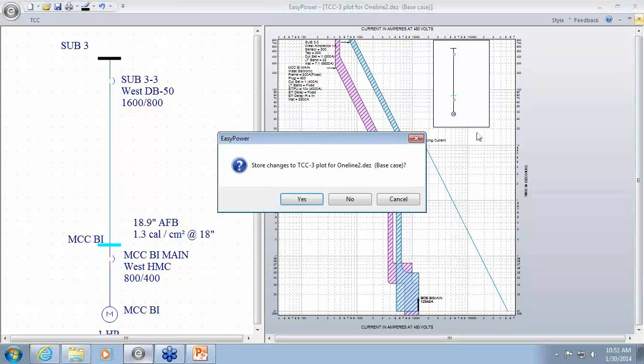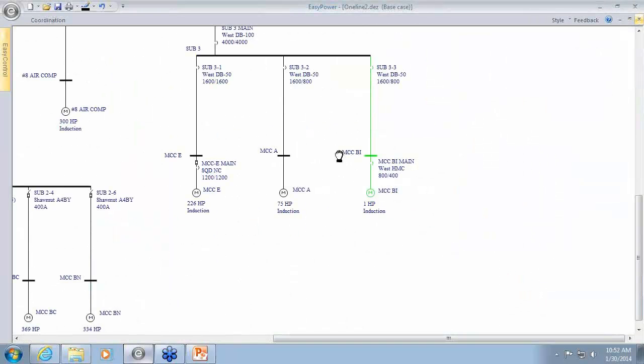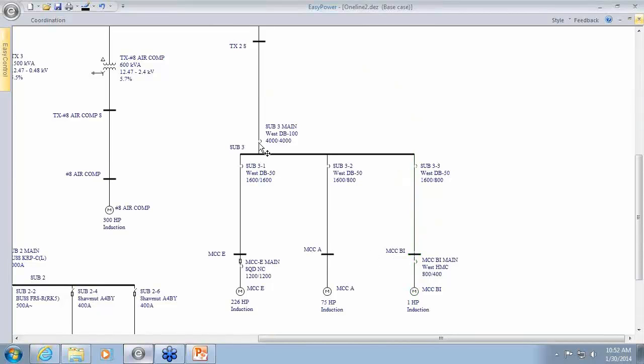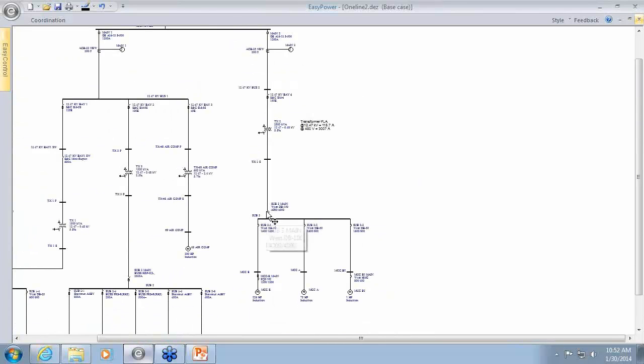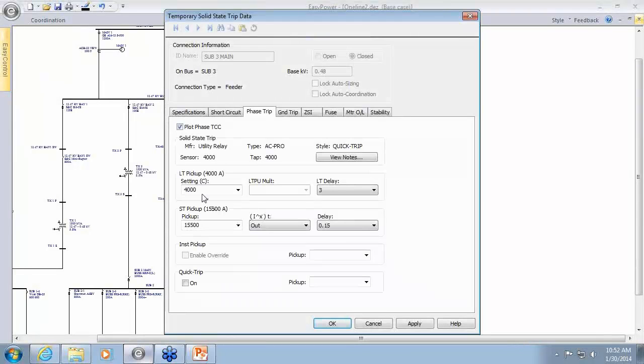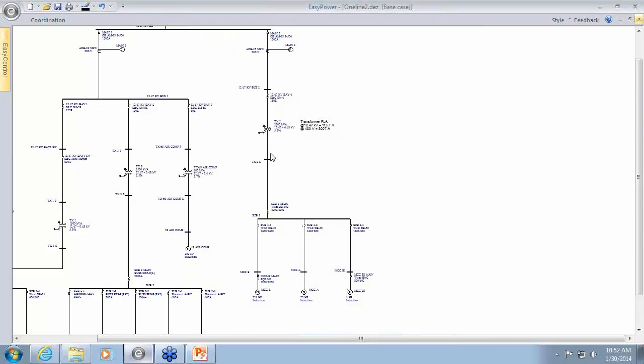Now, in this case, this facility decided that they would change out the trip unit on the main breakers with AC Pro utility relay AC Pro, retrofit these, and add a maintenance mode if necessary. And then they also changed out their old electromechanical relays with new digital relays, for the main purpose of the maintenance mode.